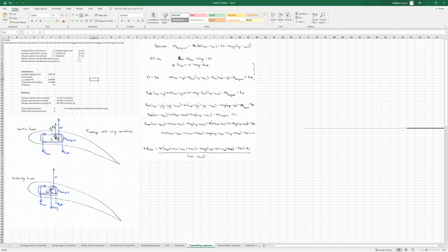As far as that force and moment itself, that's a result of both the inertial forces of the wing and the lift, that is the lift and the torque due to the lift coming in through the wing box or through the spars about that structure's elastic axis.